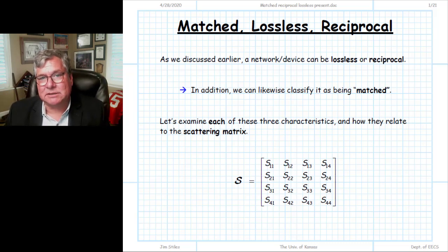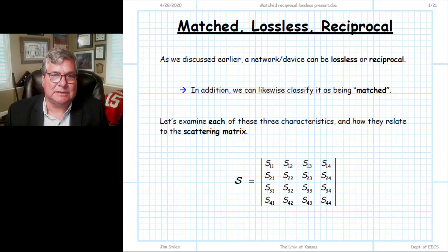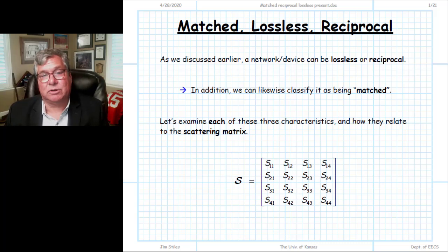Also, we talked about reciprocity, and reciprocity is a general property for the relatively simple devices and materials that we use in microwave engineering. It's hard to mess up reciprocity. And reciprocity will exhibit itself in terms of the impedance matrix being symmetric. If Z12 is equal to Z21, for example, and that's true for every off-diagonal element, the corresponding element on the other side is the same, the matrix is symmetric, then we know we have a reciprocal device, and if the device is reciprocal, it must result in a symmetric matrix.